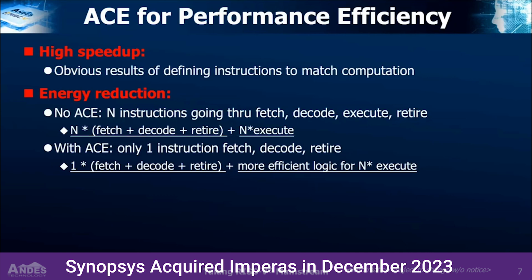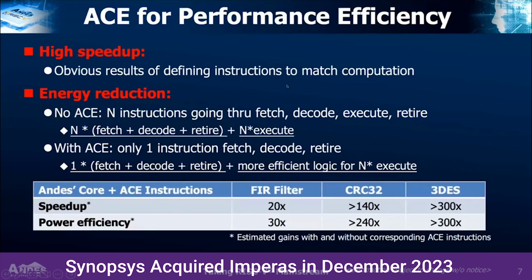I could replace, let's say, a loop that goes 1,000 times, 4 instructions 1,000 times. That's 4,000 instruction fetches and decode and execute. I could replace that with one instruction, which reduces a lot of power, so you save execution time, code size, and bus bandwidth transfers.